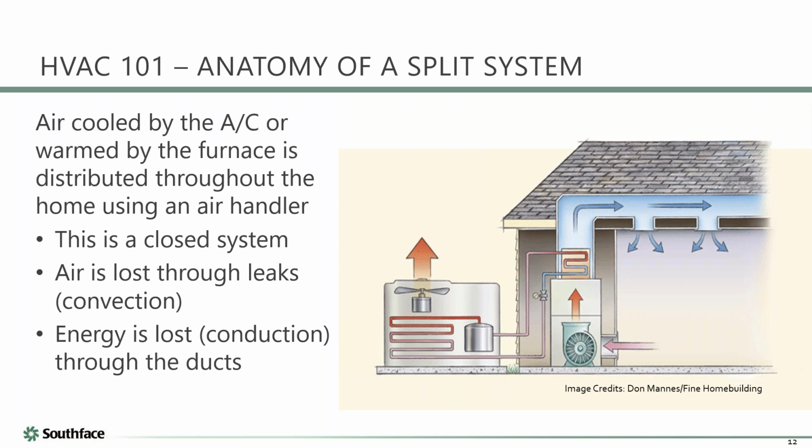But there are smarter controls that can respond to what the actual conditions are in the house. And those are usually linked to a variable speed compressor, as well as a variable speed blower. Like I know Carrier has one, I can't think of the name of it, but a lot of manufacturers have this variable capability. So in general, what we're looking for is equipment that can adjust both its blower speed and its capacity. And that usually means the compressor as well. So the higher SEER equipment, the better quality variable speed stuff, is not just the blower, it's also the compressor.